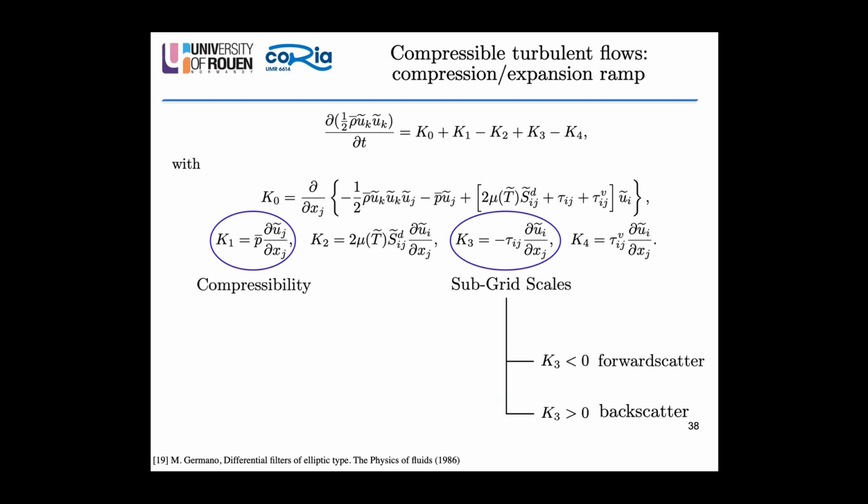of resolved kinetic energy. It's important to highlight that based on the definition of the overbar operator, you can have both filtering and averaging, so that you have a direct connection with LES and RANS approaches. So that the equations will be exactly the same. We will just change the nomenclature so that you have always resolved kinetic energy, unresolved kinetic energy, and SGS tensor versus average kinetic energy, fluctuating kinetic energy, or turbulent kinetic energy, and Reynolds stresses. But the equations will be exactly the same. So we have this parallelism between averaging and filtering for the remaining part of the presentation.